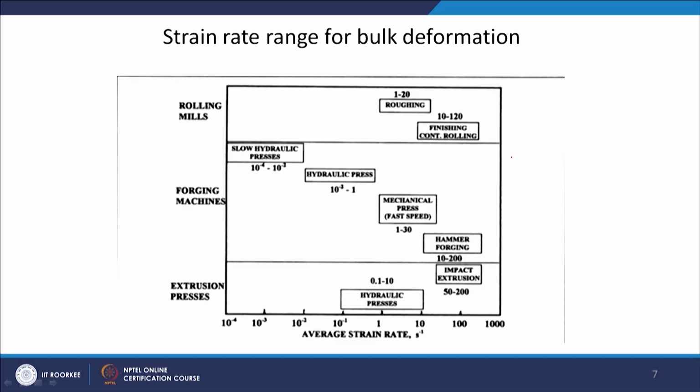You should take microstructures of all the high efficiency zones, as well as a few samples from the unstable region, and one should do a good microstructural analysis before this processing map can be used. Now, there are some applications we are going to see for processing maps.